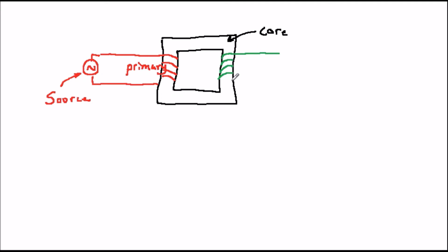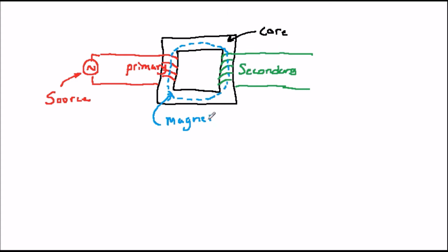The core is sometimes made of thin slices of steel. It's sliced like this to avoid certain losses. These losses are caused by the magnetic field inducing currents in the core where we don't want them, rather than in the secondary. Alternatively, the core is made from powdered iron held together by a binder. This material is called ferrite. Transformers only operate with AC electricity.